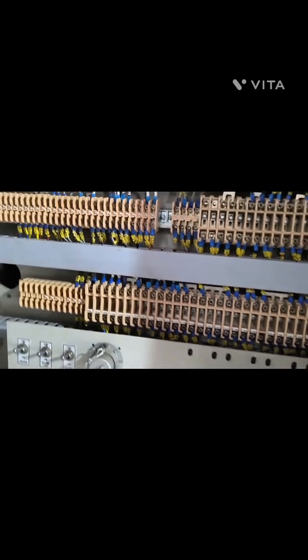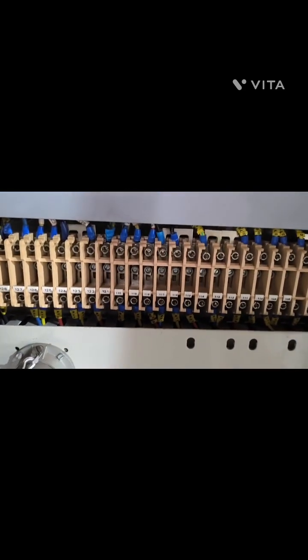And if you see here, CT will start with ABCD. So you can see here, inside A core is there. A core means it is the CT, that is the primary protection core. So for transformer differential protection it is used.